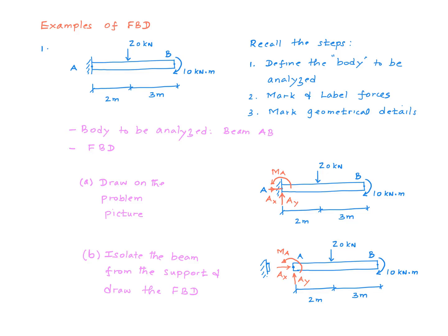One of the common questions that I get from students is, why did I draw the horizontal force to be going from left to right, and why did I take the vertical force to be in that direction, vertically upward, and why did I take the moment in the counterclockwise direction? The answer is, the choice is arbitrary. You can take any direction you wish, because at this point, we don't really know the actual direction, right? After we solve the problem using the equilibrium equation, the numbers will tell you.